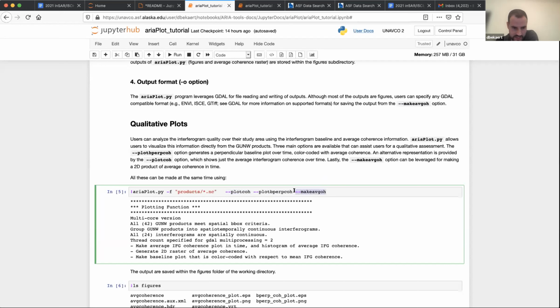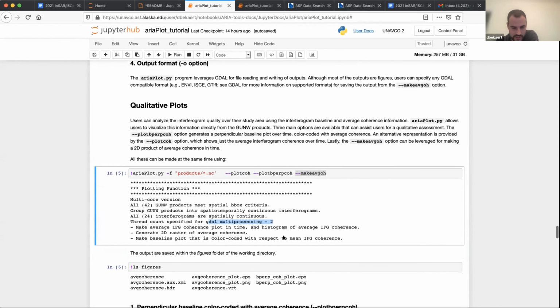Now this takes quite some time. You can actually set the multi-core to higher. I think it's -NT, number of threads. You can put that up if you want to. That's generally the water mask, which takes a while to generate, because for the water mask, we're looking at a vector data set, which we're rasterizing, or we are looking at the national land use map from USGS, which we're using to rasterize as well.